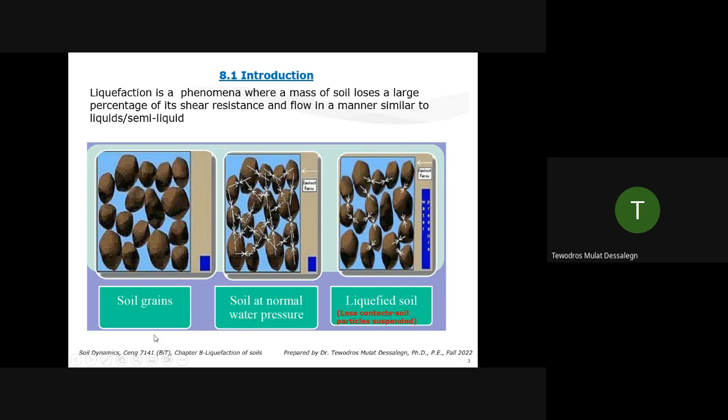See it, for example, right here. This contact is lost. There was contact here, now we don't have it because the water has high pressure because the soil above is compressing it, and the particles are suspended. And if the water pressure increases further, the water can escape and cause a sand boil.